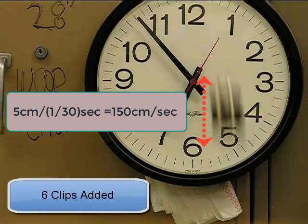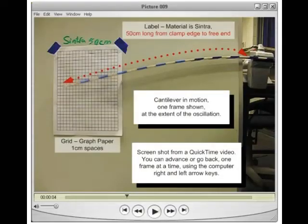As part of the tutorial, we're going to put it all together. So you set up your system in this manner. You can put little markers on the cantilever stick so you can see it better under video frame by frame analysis. And you can also put a grid in the background to do exact measurements with respect to the distance that the cantilever travels at any given time within the video.